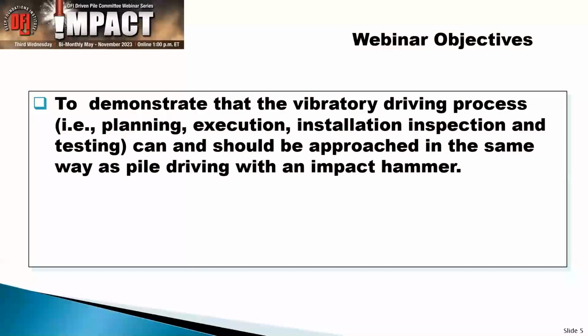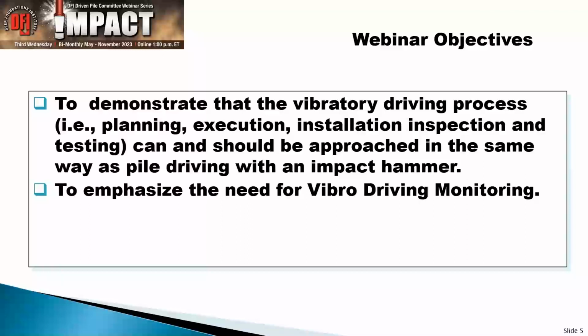What I would like to do in this webinar is to demonstrate that vibratory driving can be approached in exactly the same way that all of us are used to when it comes to pile driving with an impact hammer. You do a simulation, you do your monitoring, and then you do your data analysis, your signal matching, whatever you want to call it, your restrike that you normally do with an impact hammer. You can do exactly the same thing with vibratory driving.